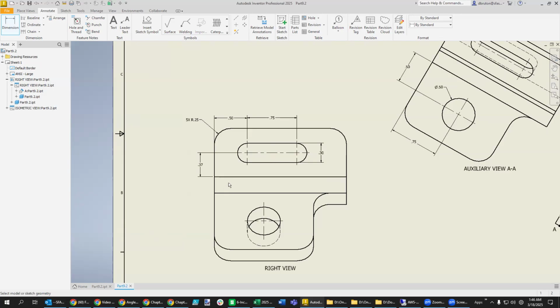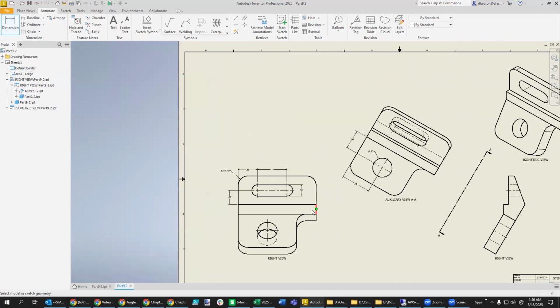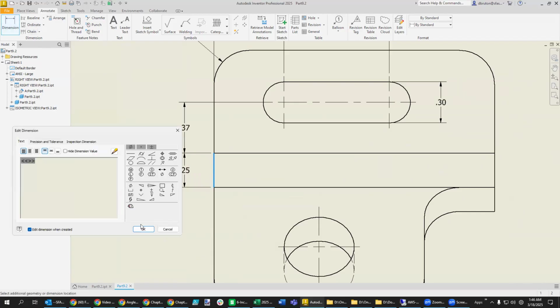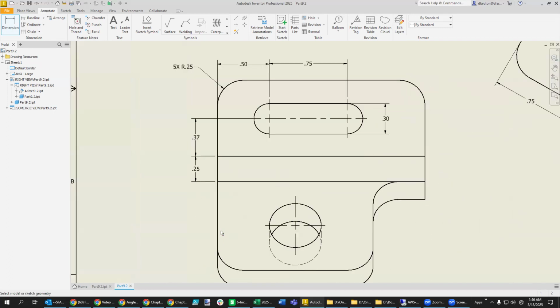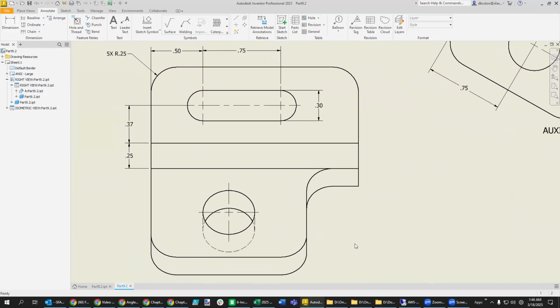Can we also say that this one right here is 0.25, or is that one at an angle? To tell about that, you kind of just look at your projection and go all the way over there. And you see that we are looking face on at that surface. So it's okay to do this dimension right here. What we should not do, though, is try to dimension this distance right here, because that's going to be a foreshortened distance. This is a slant right here. So it's going to be accurate, but not intuitive to the viewer. We need to leave it like this to show that this is a piece that's coming out from that.